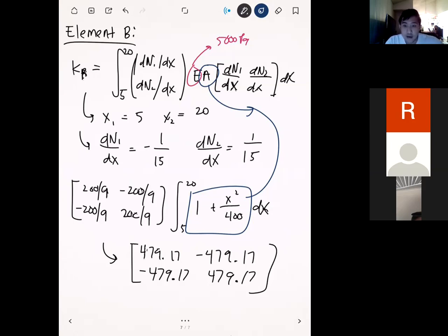All right. So the question is with anisotropic too. Anisotropic is a word to describe how material properties can change within a material. So not only the value of the material property, but also the direction of it. In this case, we're assuming that the Young's modulus is isotropic. What that means is that we have a constant Young's modulus that's the same in every direction. But this can handle those cases too. You just have to use a slightly different formulation.